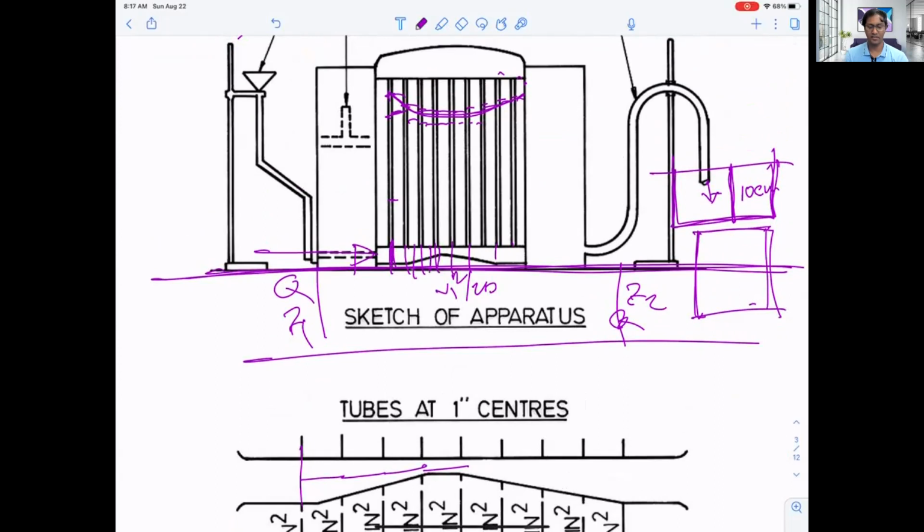So we'll change the condition, meaning change the Q 5 times. We'll collect this water 5 times, measure the time 5 times, then fill up a data sheet and repeat all these calculations 5 times. Then we'll have enough information to plot, to check what is happening to the head loss when the conditions are changing. What is the relationship with this velocity head? If the velocity head increases, then what will happen to the head loss?